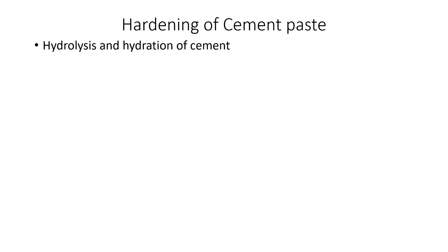It is found that C3S, tricalcium silicate, is hydrolyzed to 15% in a day, 23% in 7 days, and 26% in 6 months. So this hardening process is more prolonged than the setting process. Beyond this period, no further hydrolysis is observed up to 2 years. Similarly, the amount of water combined with C3A, tricalcium aluminate, at 1 day is 30%. It increased to 35% in a month and 38% at 2 years.